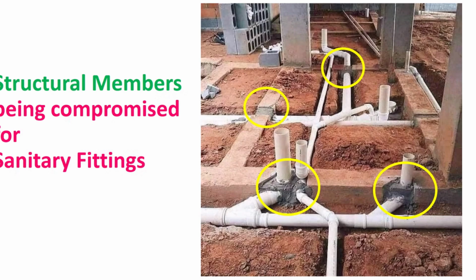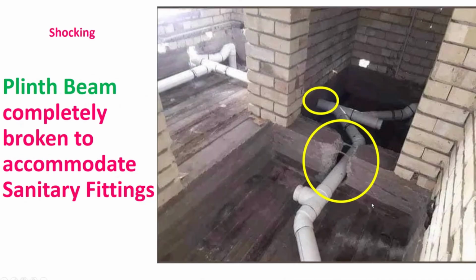This is with respect to certain thickness of footings depending on the type of masonry, plain concrete, reinforced concrete, etc. This again you can take as a reference. Important requirement: suppose you are doing a rough foundation, minimum depth of foundation not less than 1 meter. For a normal foundation it was specified as 500 millimeters or 0.5 meters. For rough foundation, NBC specifies not less than 1 meter should be the minimum depth of foundation. Clear?